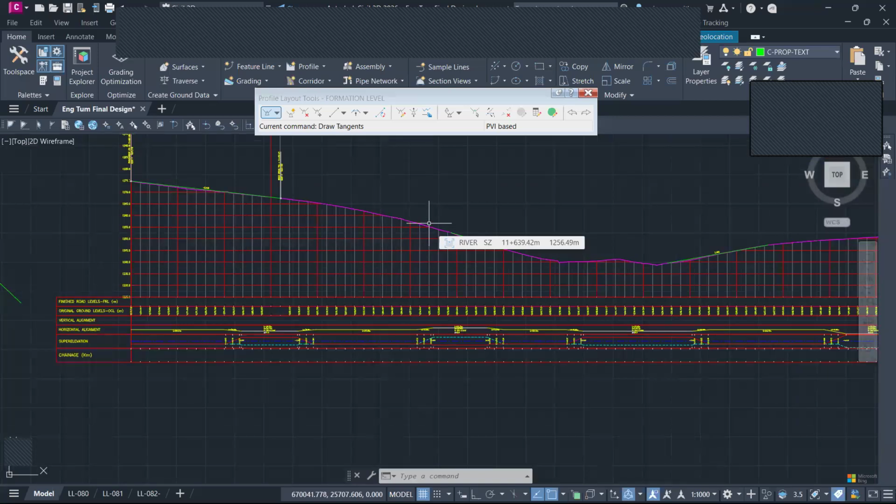When connecting the curve, we go back to our design criteria and look at the parameters that we used. The parameters that we developed were, number one, the length of the curve. The minimum length of the curve, we said it is 2 VD. 2 VD means twice the design speed. I remember someone telling me for a design speed of 80, it will be 160. That is the minimum. We note that down. We also note down the K value for a crest curve was 45.